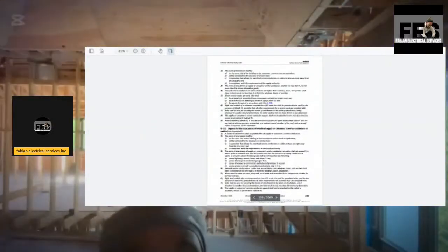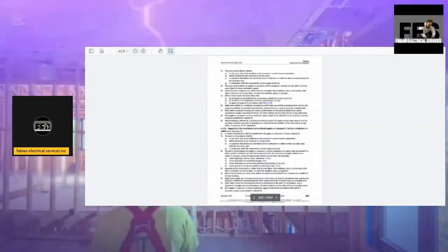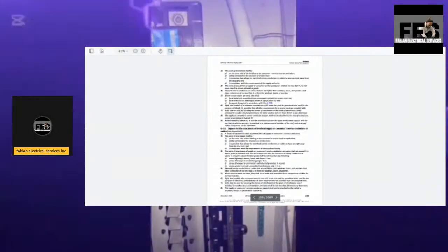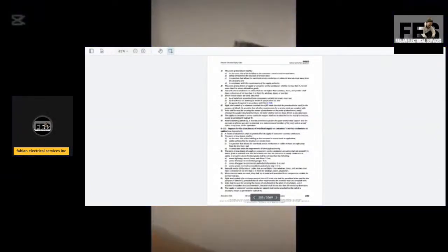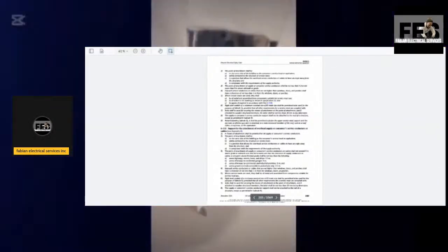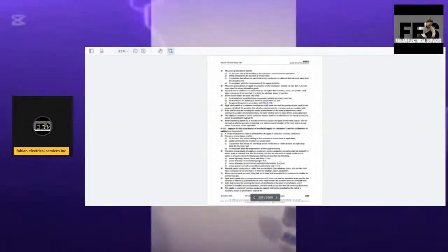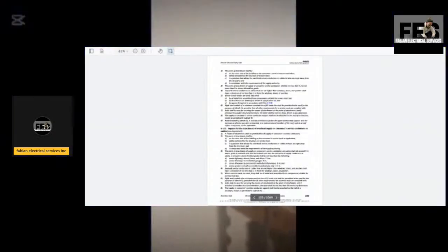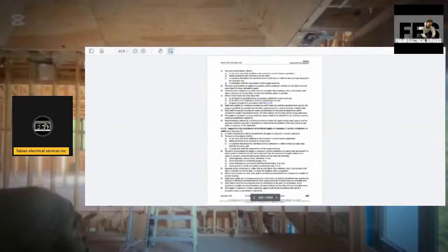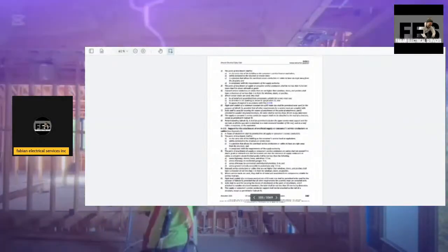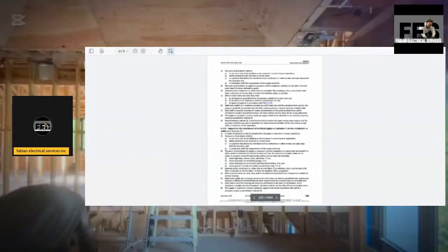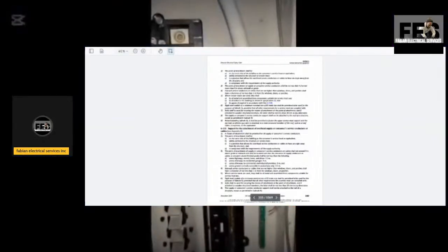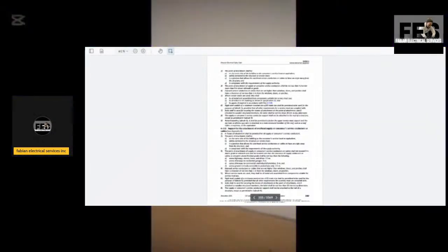The point of attachment of supply consumer service conductors or cable shall not exceed 9 meters above grade or sidewalk and shall be located such that the clearance of supply conductors or cables at any point above finished grade shall be not less than the following: across highways, streets, lanes, and alleys, 5.5 meters; across driveways to residential garage, 4 meters; across driveways to commercial and industrial premises, 5 meters; and across ground normally accessible to pedestrians only, 3.5 meters.